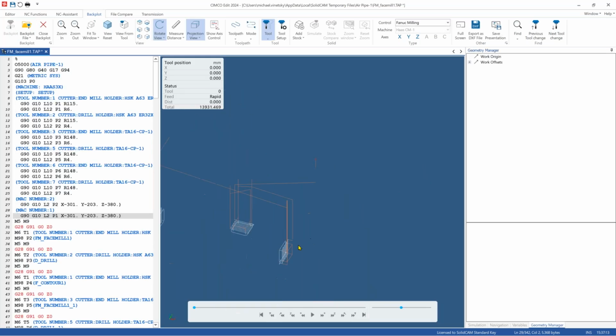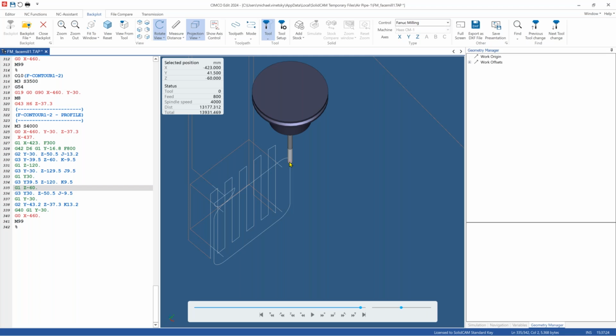We see the toolpath, and everything looks correct. If I go here to this arc, let's open this one. What I can find here is that this arc is done by K. So it works with J and K settings, and it's also in G90.